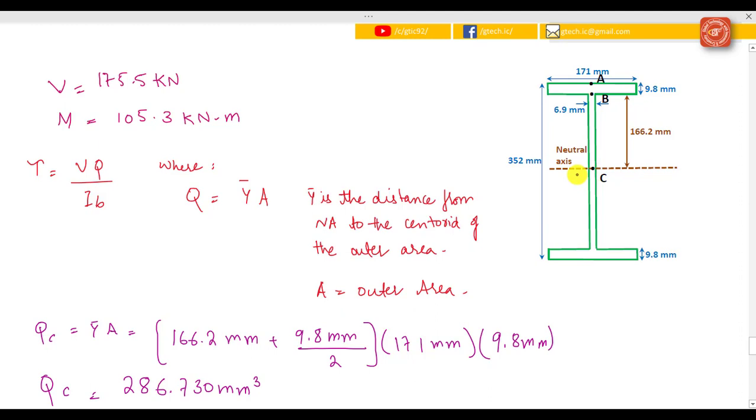So now we are going to check the last point, which is point B, where we have a combination of normal stresses and shear stresses. And we said that the junction of the web and the flange, with simultaneously high normal stress due to the bending and large shear stress, made it a critical point for investigation. So we are looking at point B.